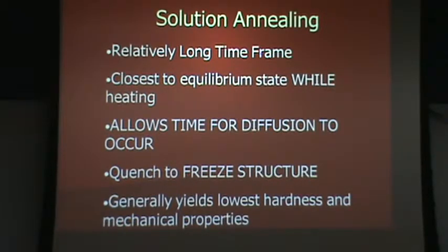But there is still some carbon present, and the chrome can react with that carbon to form a chromium carbide, just like it would in a low alloy steel. When that happens, the chrome is now tied up with the carbon, at least some portion of it is, and is no longer available to help with the corrosion resistance of the material. It's still physically present. If you did some analysis, you would still find it there, but it's not available to help with the corrosion resistance.